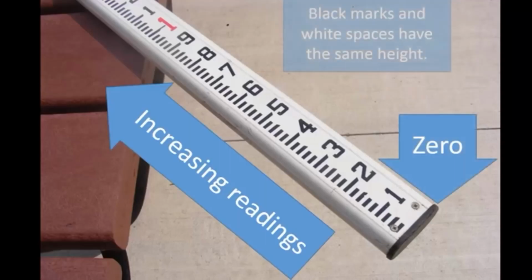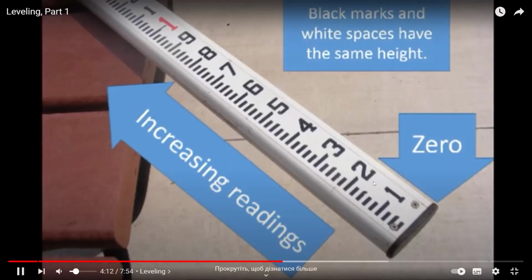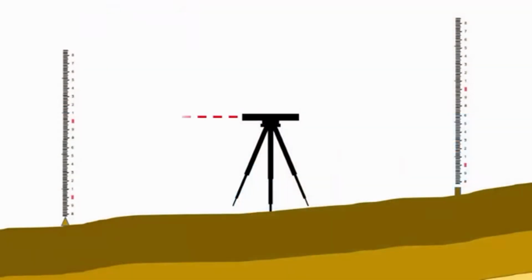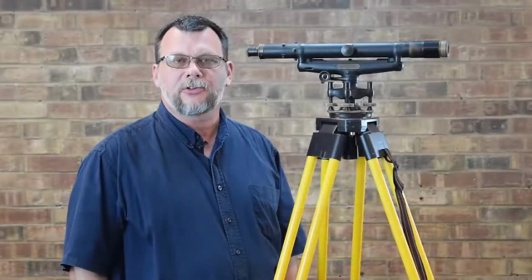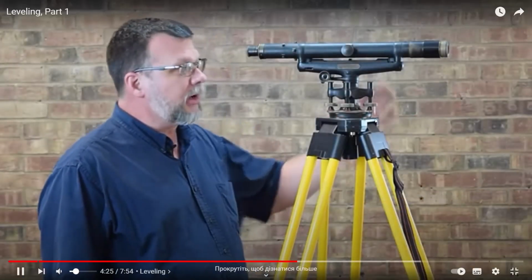This one is an aluminum rod graduated in decimal feet upward from 0. The difference in two rod readings taken from the same instrument location equals the elevation difference. Now here are some examples of optical levels.